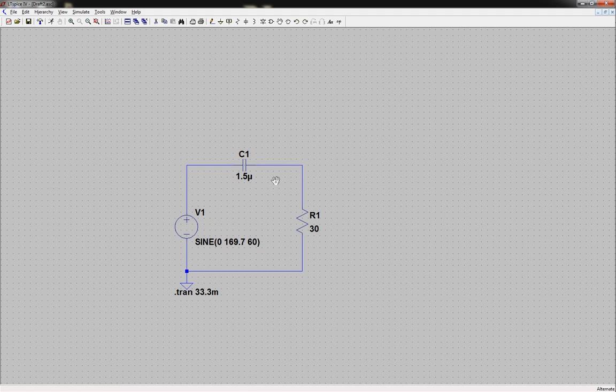Now, if you don't want it to break away, you just want to move it, wires and all, that's where you use the drag command. Then when you grab it, see how it moves the wires with it? So the drag command is a way to scoot stuff around without breaking the connection. So once again, we've got the move command that literally moves the component, and the drag command that will drag it with the wires. Okay, so I just wanted to show you guys that real quick.